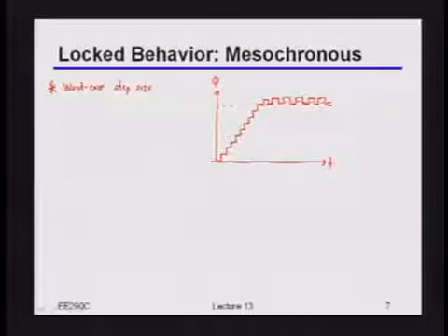You don't necessarily have a ton of control over that. I guess you could change the rate at which you're running the loop and things like that. But that dither has to be there, and I think in this particular context, it probably doesn't change the overall performance all that much. Maybe there are some second order effects in terms of the jitter filtering, but largely speaking, I pretty much have to be jumping up and down every cycle. Because if I'm not, then things are even worse. You can imagine if I'm not going up and down every single cycle, that means I'm taking multiple steps up and multiple steps down, which means the dither is even bigger.